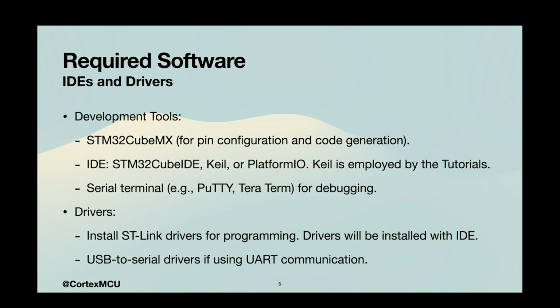There is some software that needs to be installed, including the IDEs and the drivers. The development tools include STM32CubeMX, a graphical user interface. You can configure the pins and any peripherals, link them, configure them, enter some numbers, and enable or disable all kinds of configurations.